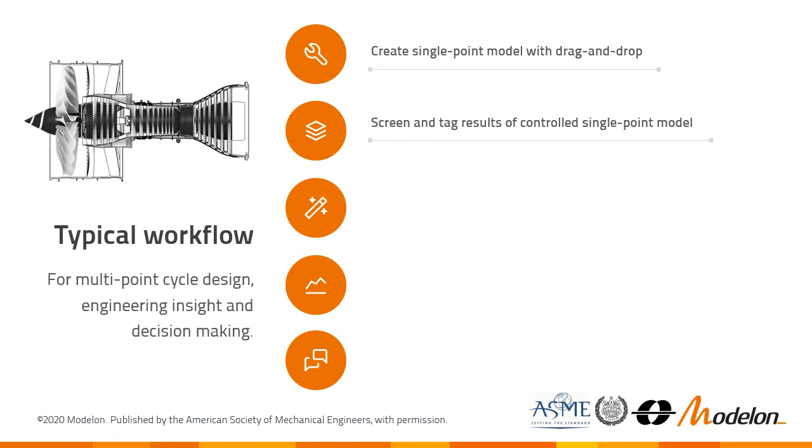These will be useful then later on when we're using more complex models because the single point results are usually easy to converge, and more complex multi-point schemes can require some work on initialization. So if we tag the single point results here, we can reuse them later on to initialize the first few simulations of the multi-point setup.